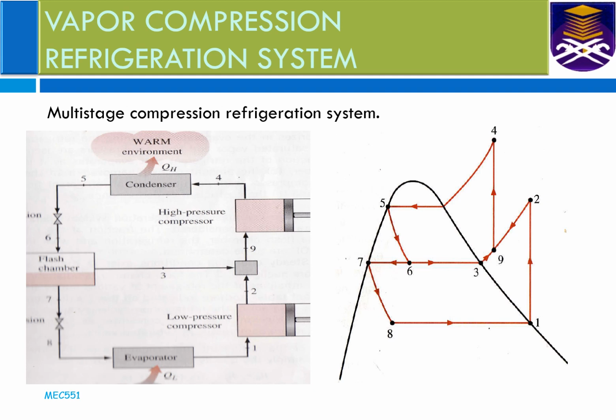After the condenser, the working fluid will pass through a first expansion valve, and it will enter into a flash chamber where part of the saturated vapor will go into the mixing chamber.